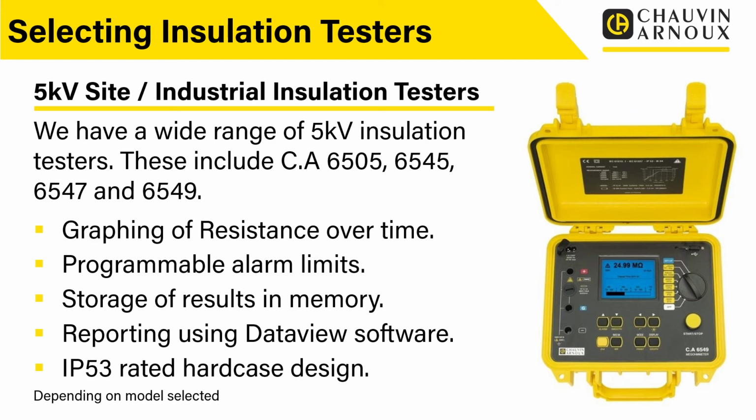Now we can also set programmable alarm limits. So if the insulation is below a certain value, it will give you a warning, so you don't have to look at it specifically and read. You can set up the alarm. So if you're carrying out a lot of tests, maybe on motor windings, you can set the alarm, listen out for the alarm, and it will tell you, rather than you having to keep an eye on the screen all the time when you're doing it.